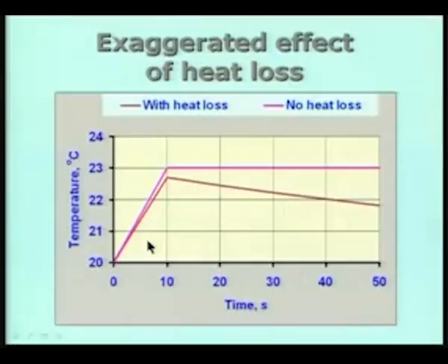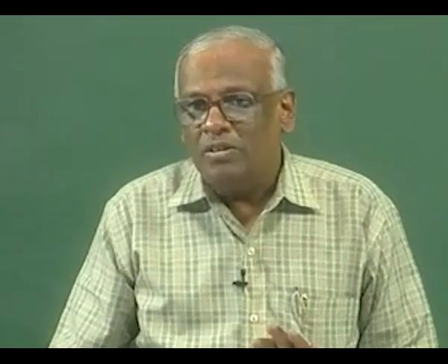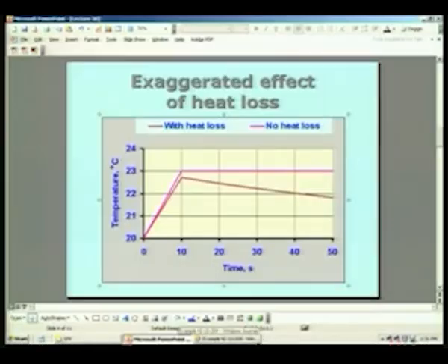Now, before we do that, let us also look at the expression we had. We had an integral of T minus T1 dt. If you remember, there was K multiplied by the integral from 0 to t of T minus T1 dt, and that can be obtained as the area under the curve during the mixing process. This is the curve, actually it is almost a straight line. So, half of the base times the altitude gives the area under this curve, and that is going to give me the integral part. The K part is going to come from the cooling curve. So, let us go back to the board and look at this in more detail.